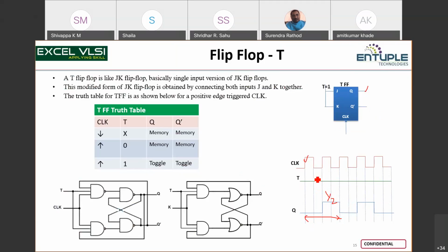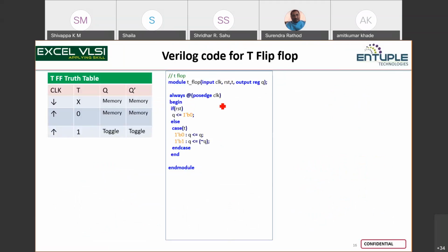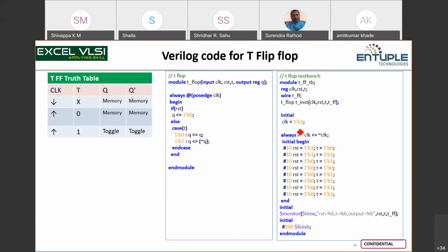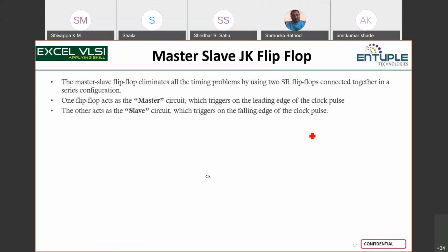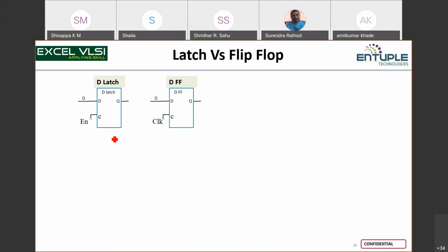It acts as a frequency divider. So whatever one clock cycle, it became half clock cycle here. Two clock cycles you need in order to make one clock cycle here, right? That's how the T flip-flop works. Okay, so now this T flip-flop and the modeling, so this I will push. Yeah, this is of interest.